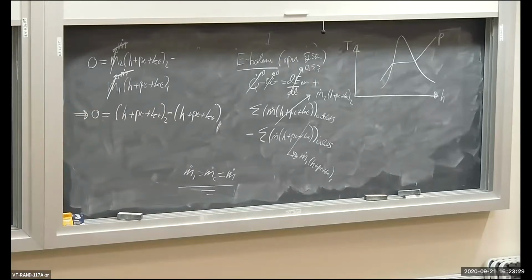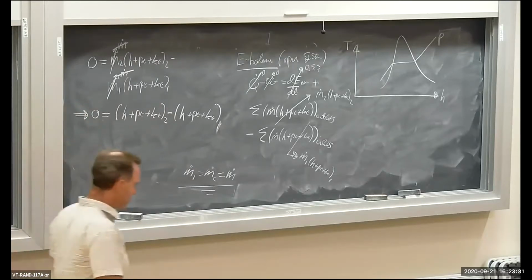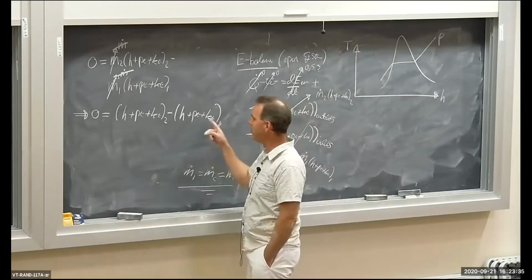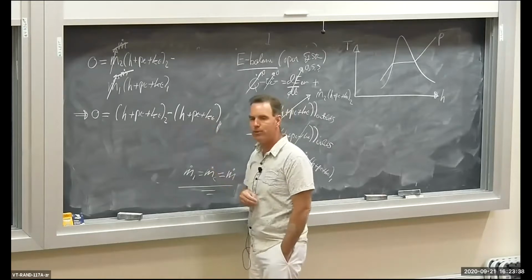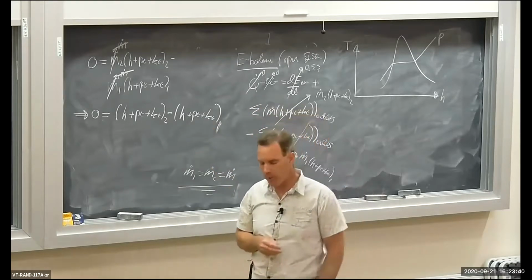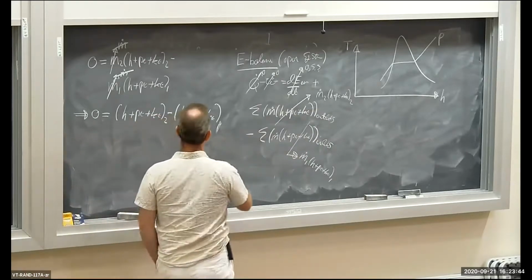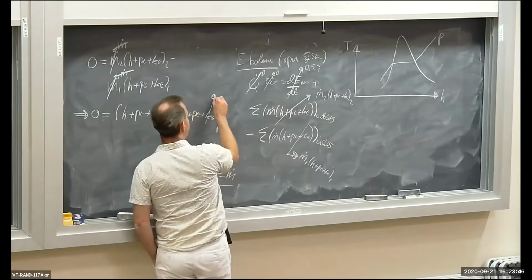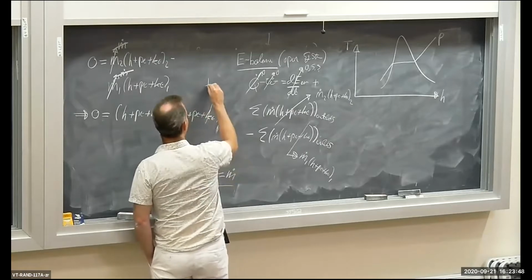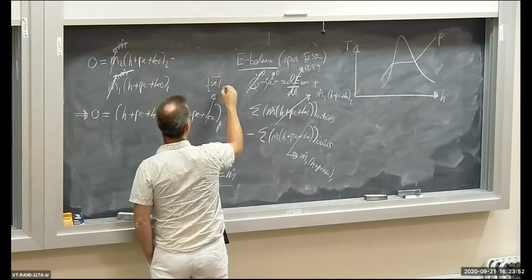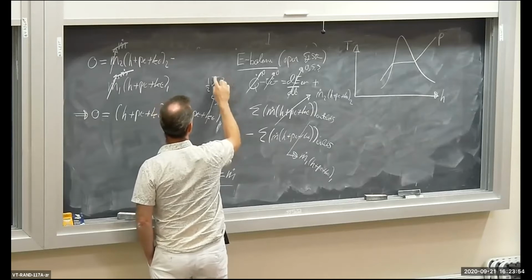Can we get rid of anything else? These kinetic and potential energy terms. The kinetic energy terms at the inlet and the outlet, that's specific kinetic energy. Those have to do with the average flow velocity. So like this guy here, KE at the inlet, this is going to be 1/2 times an average velocity at the inlet squared.